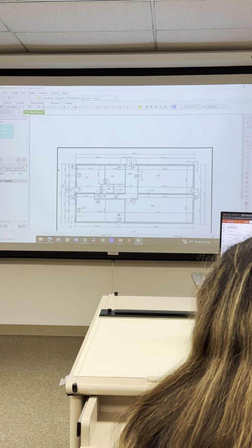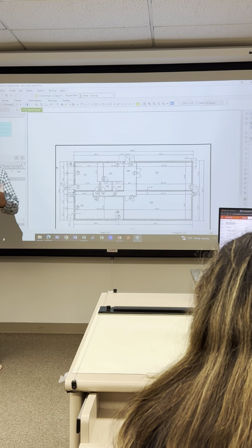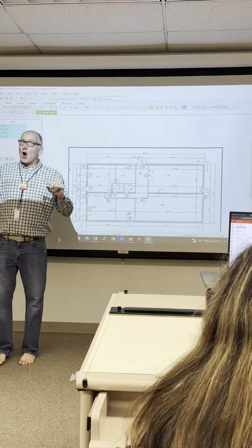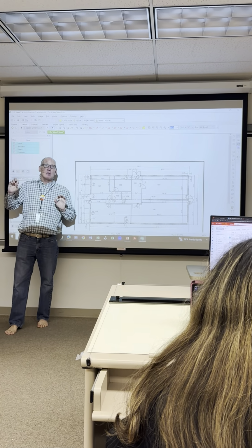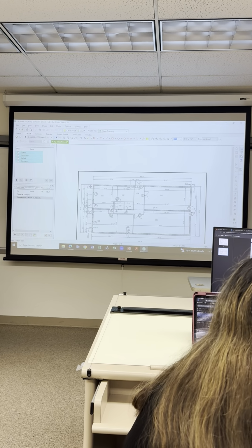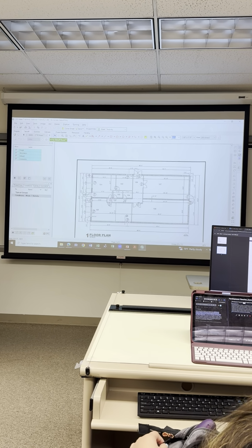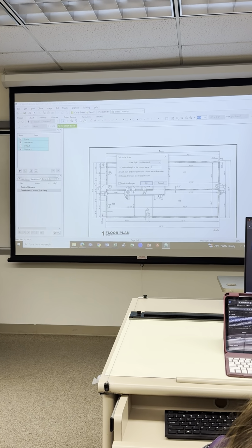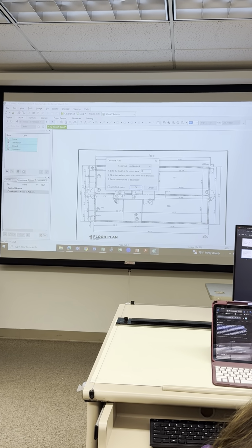So here's my drawing. I want to now move on. We inserted 2 drawings, or I'll say more than 1 drawing. We have our next step, always next step, do your scale. When we grab our scale, it's easy on this drawing because I see a dimension. We go to edit, calculate scale. I see my longest dimension is 80 feet.